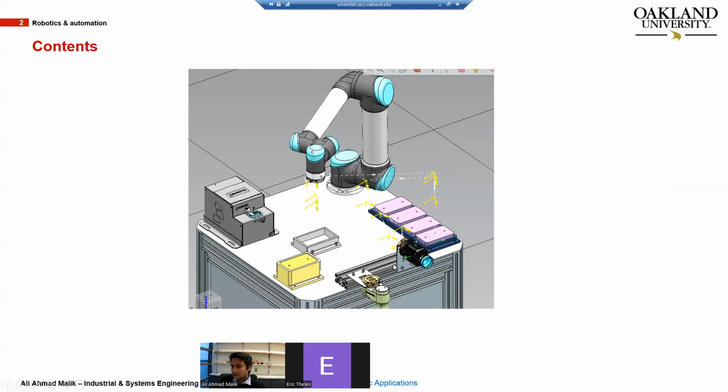And then there are these tools. I hope you remember I had shown you a video in the first class of how this technique works. So there are three components. Maybe I can show you. It is something like this. There are two of these: the tool-side or gripper-side component, and then a very similar component is attached to the robot, and the robot component fixes into it. This is attached to the gripper, for example, or the screwdriver, and then the robot can pick the tool more easily.